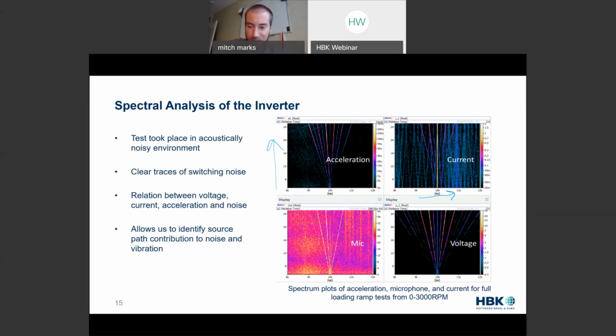And what I found, being again the motor guy, is that when we start doing acoustic analysis, because this is really looking at acoustics, this is the inverter switching at 10 kilohertz. Voltage gives us a really fantastic signal for translating to acceleration or microphone, because it doesn't have that filtering, it doesn't have that noise source that's getting caused through the sensor. It's just this really pure signal that we can really start to look at acceleration. But we get the full source path.